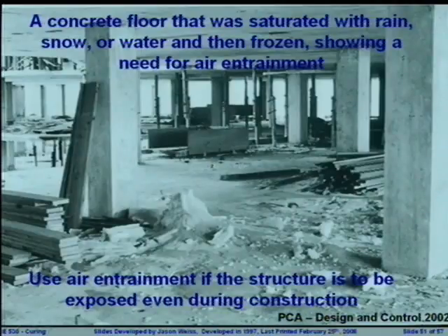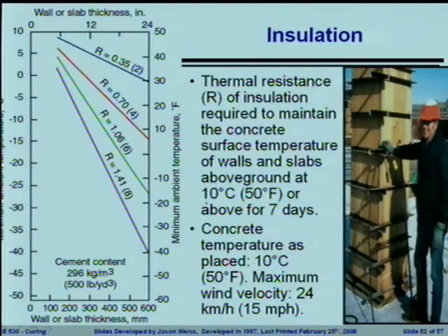You may have said, well, I assume that this is going to be constructed during July. Delays happen on construction projects. Once or twice that has happened in the history of mankind. So they may be putting that concrete out, and it may be exposed to freezing and thawing during placement. Frequently, you will see people entrain air in this concrete just for kicks, because it's going to help with the economics and because it may undergo a freezing at some point.